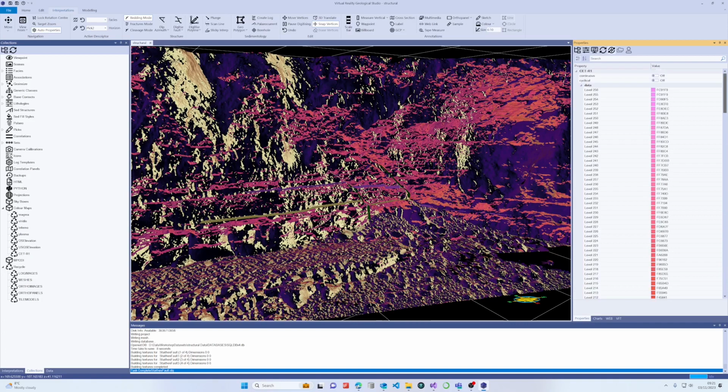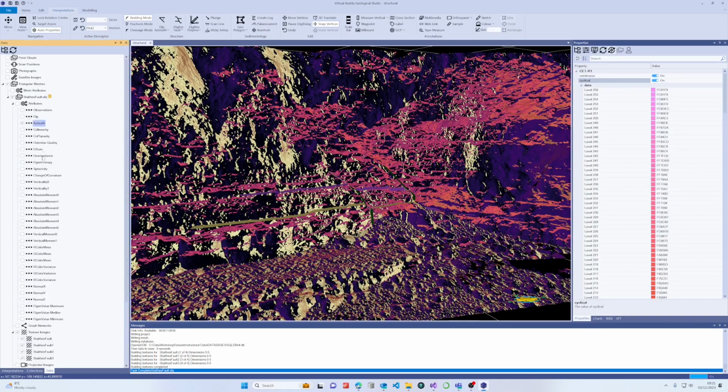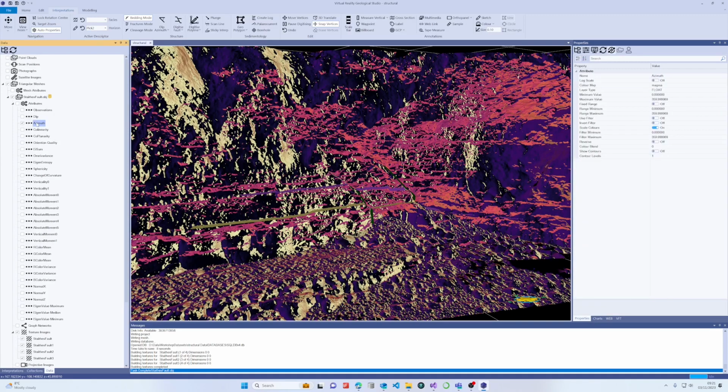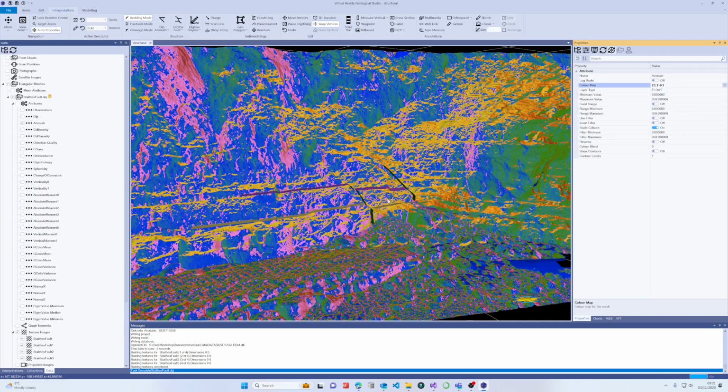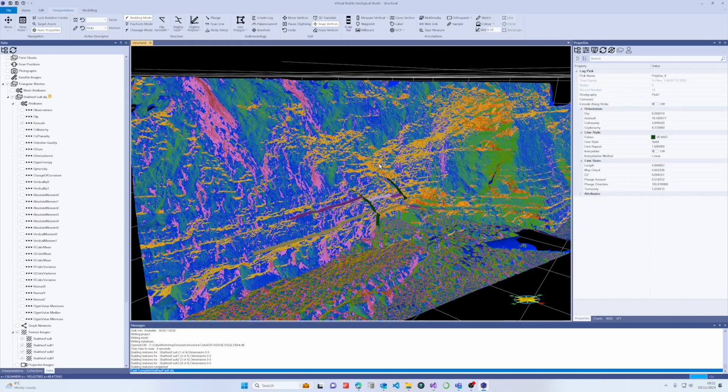It's got a name at the bottom there, and we switch on continuous and cyclical. I'll go back to the properties of the attribute, the azimuth attribute, and change the color map from the default to that cyclical color map that we've just brought in. And you see the color and the display changes straight away.